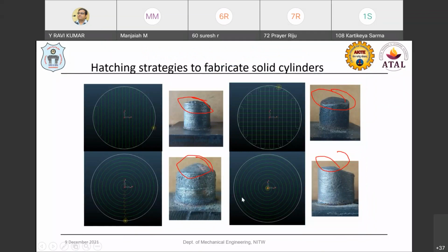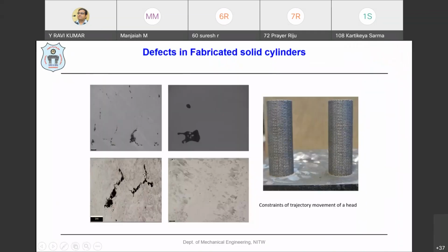And when you take up the spiral, the molten pool is flowing from one direction to another direction. Where we have the linear bidirectional, we have the intersection between one layer and another layer. There these defects are going to take place. That's why we need to address this. Once you optimize the process strategies, only then can you avoid such defects, and with these strategies efficiently manage this kind of component.